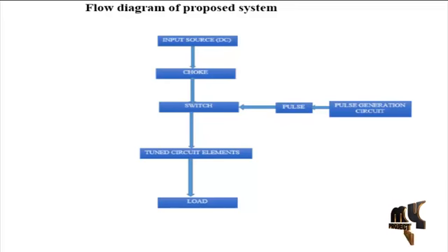Many communication applications use tuned circuits. These circuits are assembled from passive components in such a way that they only respond to a narrow band of frequencies. Applications include radio receivers, RF amplifiers, local oscillators, IF amplifiers, filters for frequency division multiplexing, and so on.